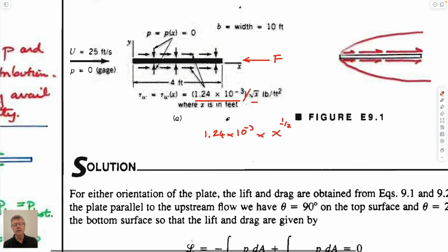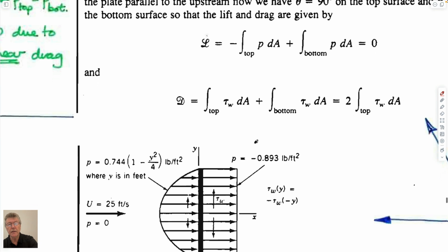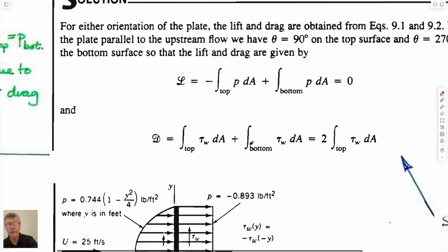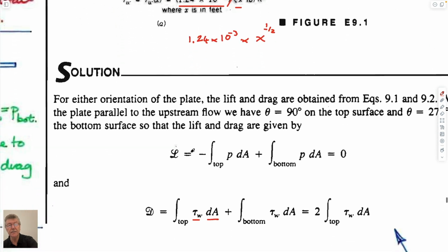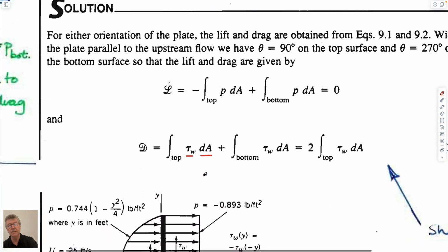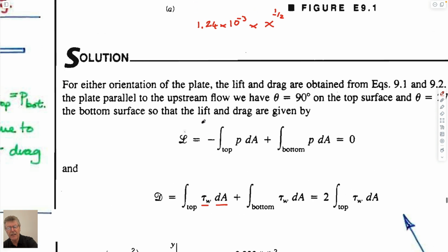But if you take this relationship and look at this equivalent term here, you can merely evaluate that by taking, in this particular case, the area over which it acts, and we have this both on the top and the bottom. So the angle here is going to drop out for the shear force because it's 90 degrees, right? The normal to the surface is 90 degrees. And so if we know the magnitudes of these stresses, we can calculate it.